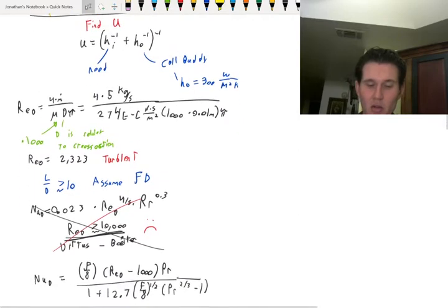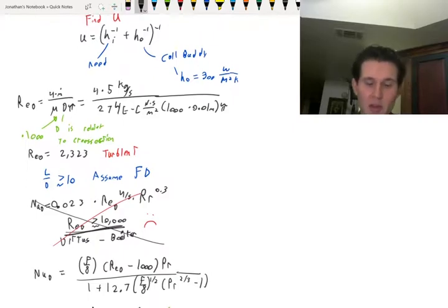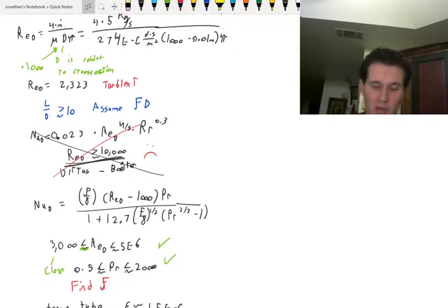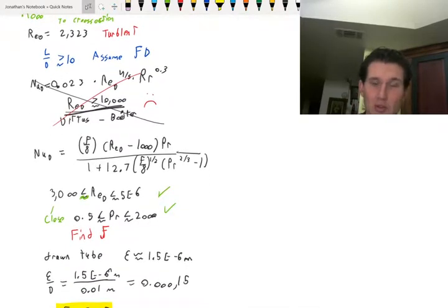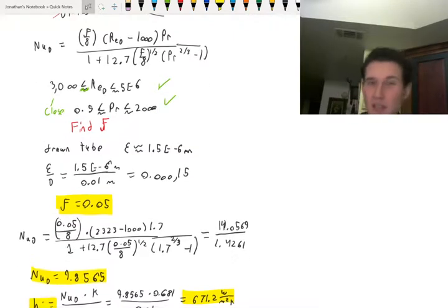We needed our overall heat transfer coefficient, and we needed the internal convection coefficient and the external convection coefficient. The external convection coefficient we called the buddy. The buddy modeled it for us. He gave us the value. We found the internal, went through the Reynolds number, found the right Nusselt number equation. Remember, the right Nusselt number equation is the one where all the conditions for the equation match up. In this case, it matched up pretty close and it was the best option at hand.